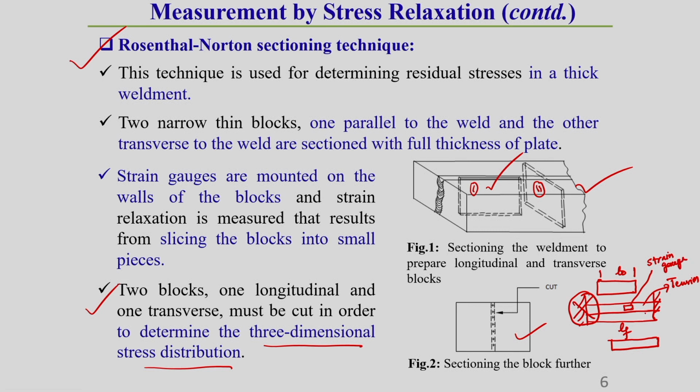So we know this, due to this locking in by the two supports or elongation, inside this specimen there will be tensile strain, correct. But once we remove this support from here, the elongated part will compress and return to its original initial length, correct.